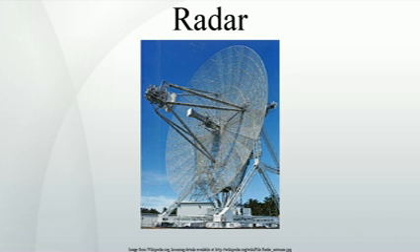Since radio waves travel at the speed of light, accurate distance measurement requires high-performance electronics. In most cases, the receiver does not detect the return while the signal is being transmitted. Through the use of a duplexer, the radar switches between transmitting and receiving at a predetermined rate. A similar effect imposes a maximum range as well.